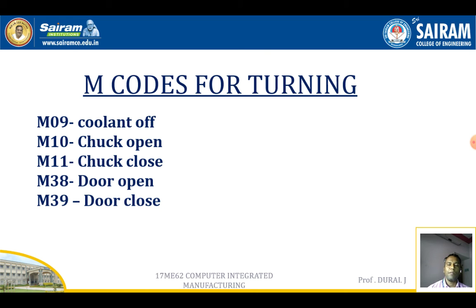Then comes the M11, chuck will be closed. That means the workpiece is rigidly fixed in the chuck, so it is ready to start the operations. That is the use of the M11 command, chuck close.